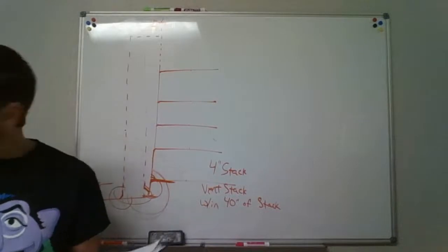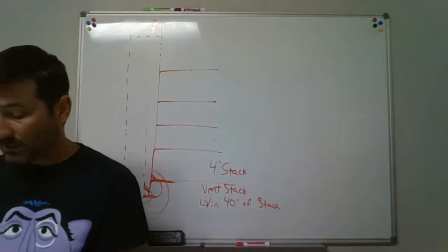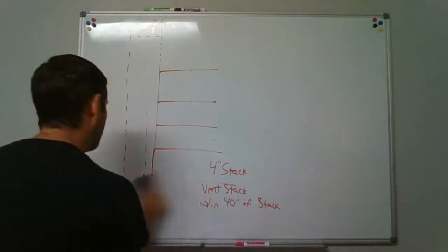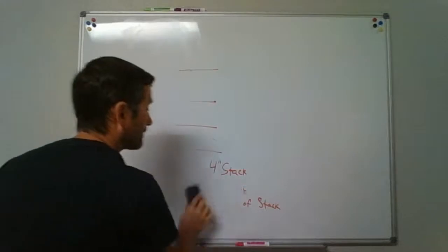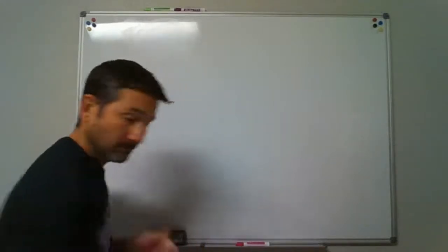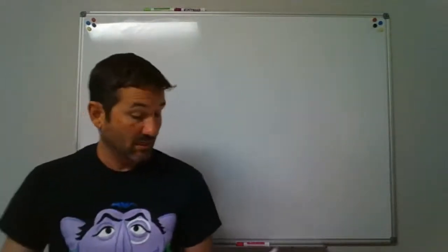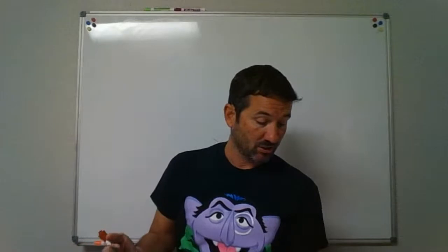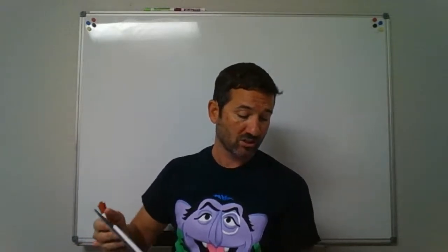Okay. Vent connections and grades. Vent connections and grades will be the next thing we take a look at. Connections. Individual branch and circuit vents shall connect to a vent stack, stack vent, air admittance valve, or extend to the open air.